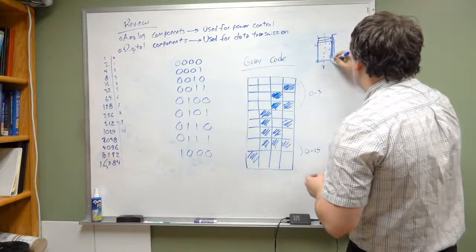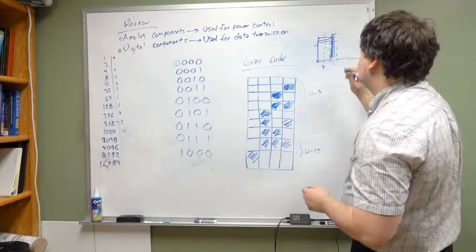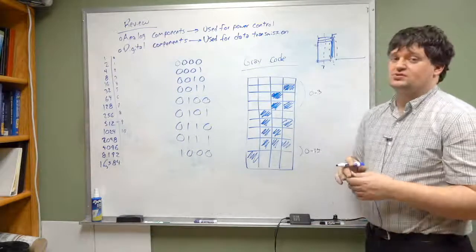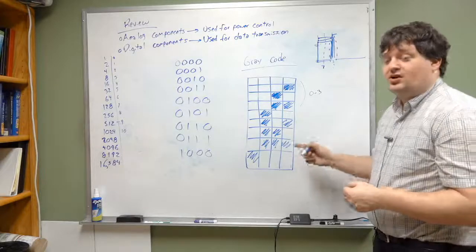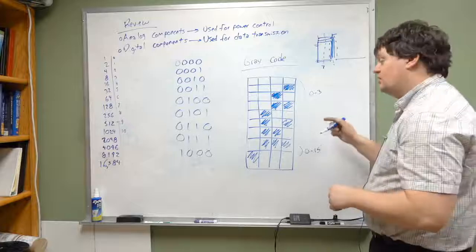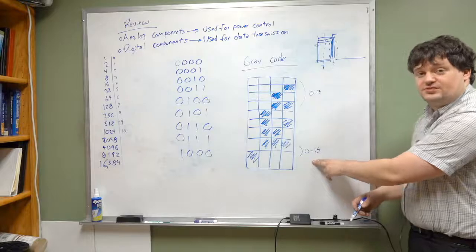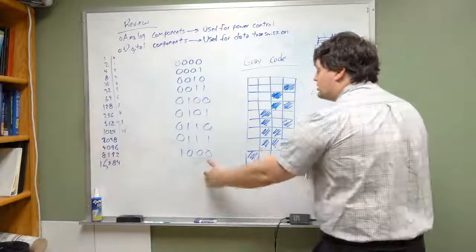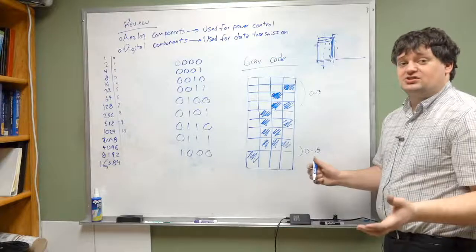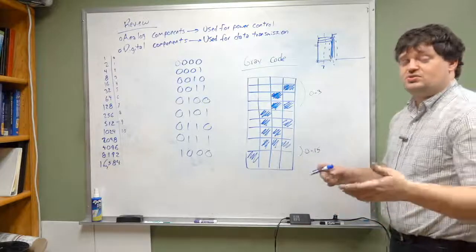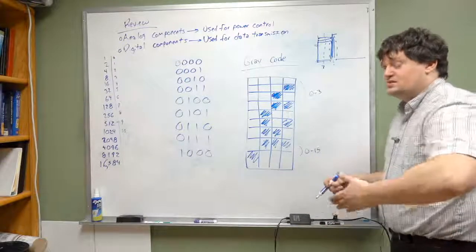And there's this transition period right here where if I have a clock signal that reads it, you do not know which of those signals are going to be on. Okay? We don't know which of these is going to be on and which one's going to be turned off at that moment, which is the reason why we could be reading anything from 0 to 15. And the larger our numbers get, the bigger this problem becomes. Okay, the transition between 15 and 16, you could be reading any number between 0 and 31.